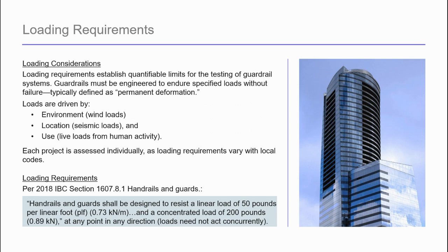That uses a small urban scale model that's scaled down with pressure measurement devices attached to those buildings that determines pressures on specific areas or pieces of the building. This is allowed by code in lieu of calculated wind loads, except in New York City, where the greater of the wind tunnel study and a calculation must be used.